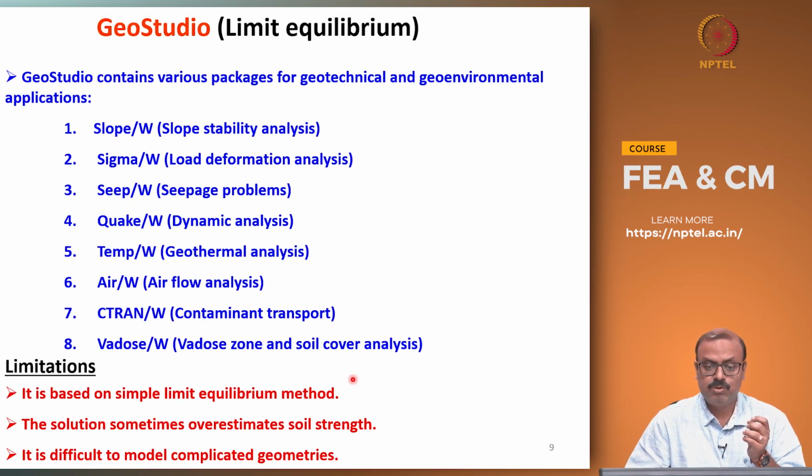Then comes GeoStudio, which is not a single software, it is a collection of various software, and principally they are based on the limit equilibrium type of approach. This class of software has a wide variety of applications, with packages meant for geotechnical or geoenvironmental usage, such as SLOPE/W for slope stability, SEEP/W for seepage problems.